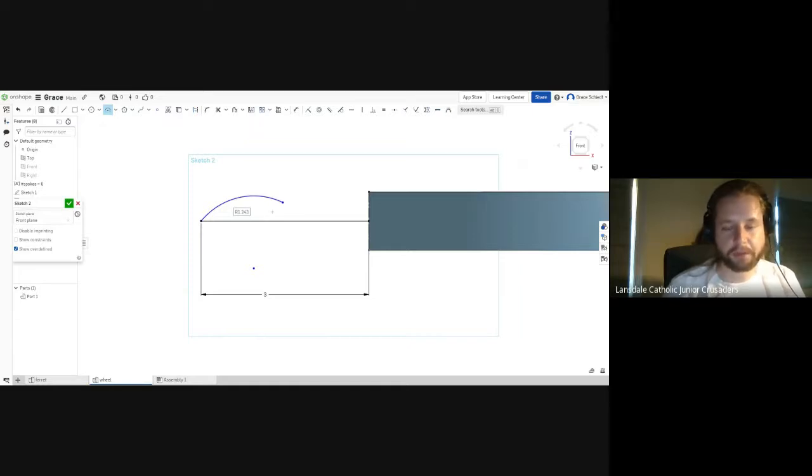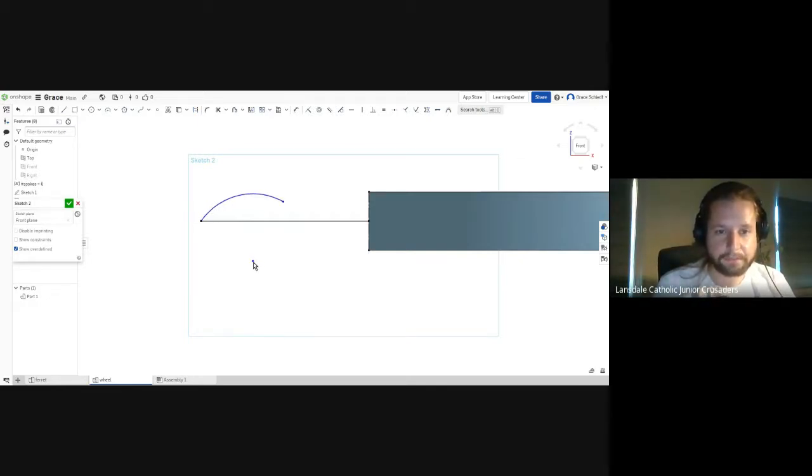This is a trick. We're gonna make sure that this circle comes to a perfect radius at the edge. Do you see the center point of that circle? It's at the bottom. It's kind of by the 3. You're still actually creating a 3-point circle. So click on that dot, and then click on your center line, or bring it up to your center line. That's fine. And make them. There you go. Perfect.